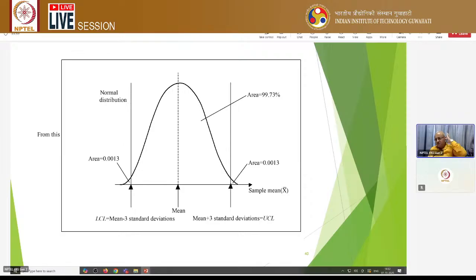So what is the basic concept of the control chart? If I am taking the measurements of some quantity in the industry, like I am turning some shaft, and I am taking only the final diameter. That final diameter may be distributed in any way, but when we take the measurement, let us say instead of one measurement, daily I take 5 measurements, random type of thing. And I take the average of those 5 measurements. I plot that average. Next day I take another average. So we keep seeing whether at any time it goes out of the limit or not. If it goes out of the limit, then we take control action. So that means we have set some limit, and this is how we take the corrective action. So this is the concept of the control chart.